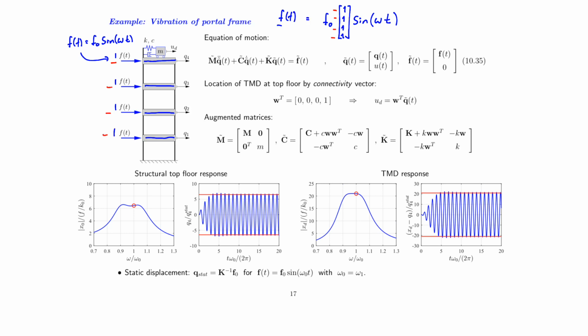Then we also introduce our tuned mass damper. It is governed by the TMD mass m, and we find the mass ratio in terms of the modal mass when we normalize top deflection to unity, and based on the mass ratio mu, we can find omega d to give us k and zeta d to give us c. Now I want to run some simulations to show you the correspondence or the similarity between a frequency response analysis with a dynamic amplification curve as a result, and time simulations that I have been conducting using the Newmark method that we're going to consider in the next lecture.